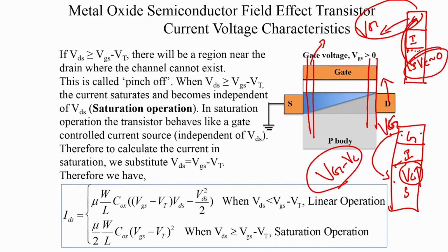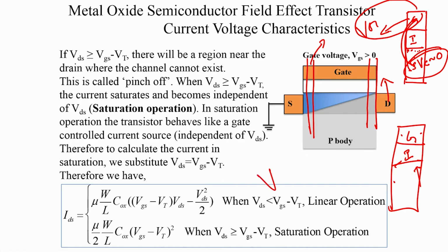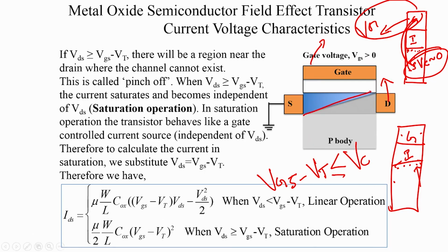Now, Vg minus Vc is negative, or let us say 0, or in fact we should be looking at the potential above Vt, because we have to cross Vt to get this. So, when you have the condition of VGS minus Vt being less than the channel potential, you cannot have an inversion layer, there are no electrons there. As we start heading towards the drain, the channel should taper off, and the moment VGS minus Vt becomes equal to the channel potential, there should be no more electrons, and the channel would simply taper off. Okay, you will not see electrons there anymore. And this point where the channel tapers off is called the pinch off point. It is a technical term, it is called pinch off.